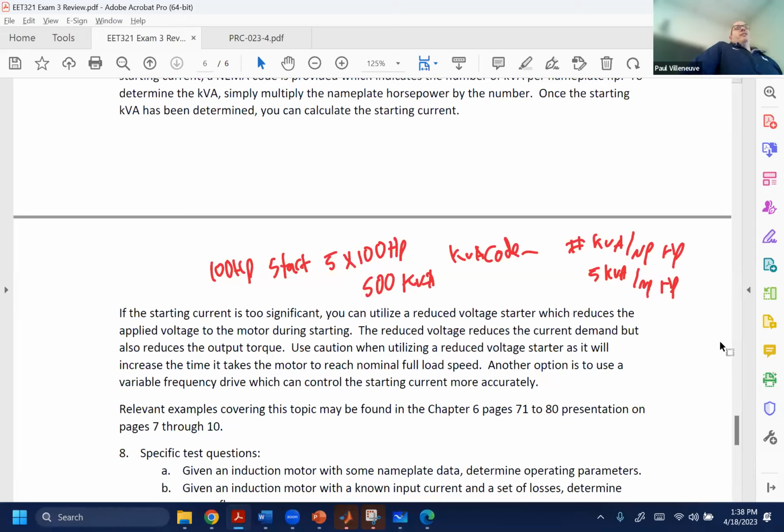So electrical fires happen because it is flammable, but they do have some flame retardant additives in there. But you don't want oil going all over the place, because even though it is biodegradable, it's still a pain in the butt. If you have a substation with oil all over it, you've got to clean it up because it's just not practical to work. So they do have containment structures and fire suppression systems. You don't need as many fire suppression systems as they used to because the oil is so flame retardant.